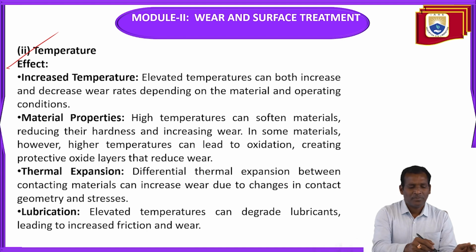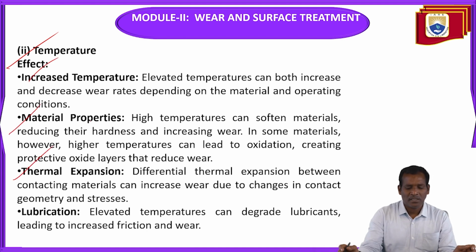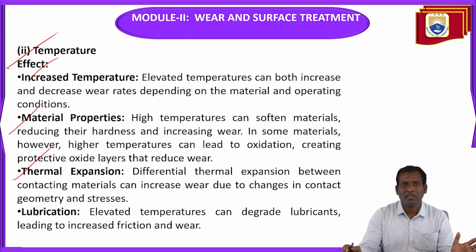Thermal expansion: differential thermal expansion between contacting materials can increase wear due to changes in contact geometry and stresses. Lubrication: elevated temperatures can degrade lubricants, leading to increased friction and wear.